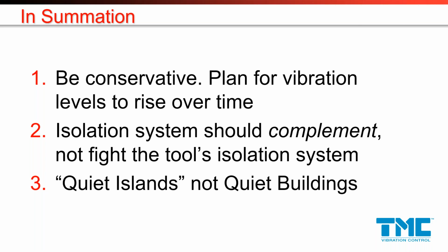Okay. Next one, can these vibration attenuation techniques be used to compensate for general instruments over cantilevers or on higher levels in a building, or are these techniques mostly reserved for high precision instruments? These are strictly to isolate high precision instruments from low frequency, low amplitude building floor vibration. What we're not doing is anything for a gross seismic event. This is not any sort of an earthquake mitigation structure.